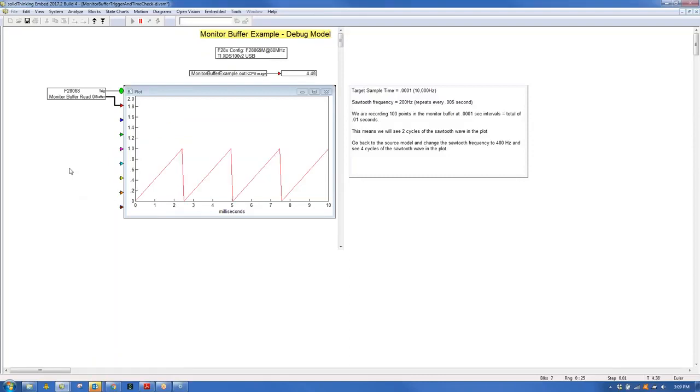So this is a very accurate way to capture the data off the target interface. It's essential for doing any kind of work on the target interface. At the motor control level, you're going to need this kind of accuracy to ensure the PWMs are working properly and that your sensors are working properly, and to be able to see it and plot it out.